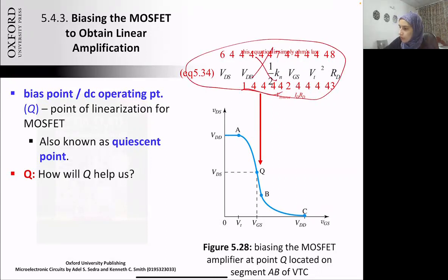It's not important. What I want you to look at on this graph here is basically in the large signal analysis, this VGS is free to move here and there as much as it wants to move. So wherever this VGS is lying, we are going to find also the VDS there.